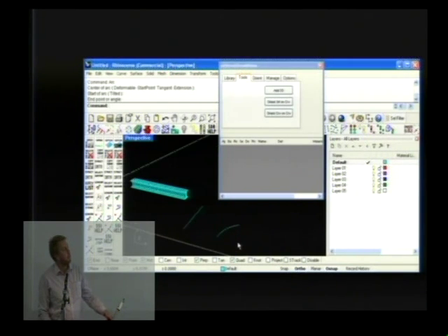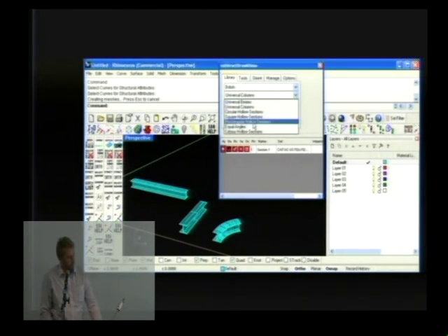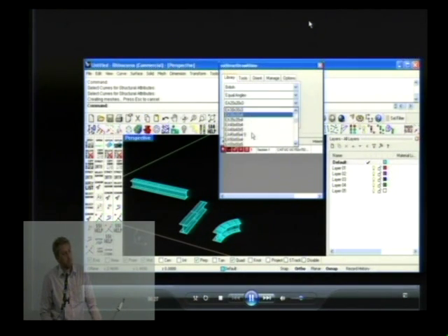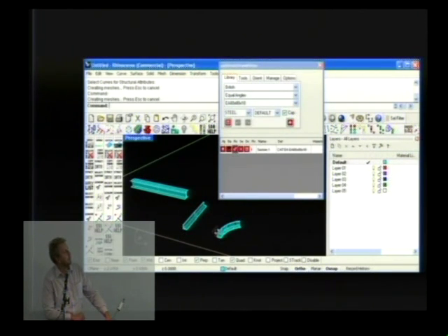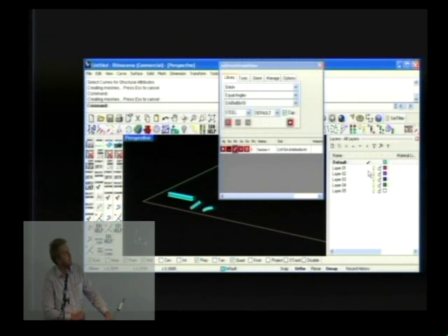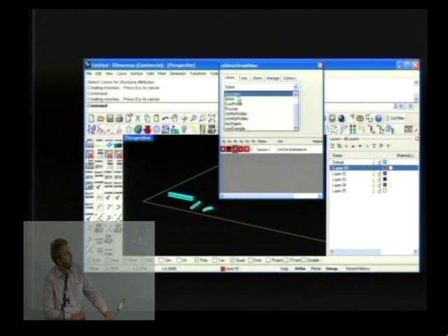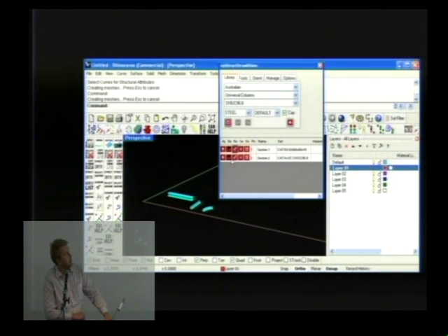When dealing with structure and using these in projects, stadiums, bridges, etc., part of what I had to develop was profile libraries and databases of sections that you'd use. Obviously, I've tried to pick the best aspects out of a number of software programs that I've used to create a better tool. It also works parametrically, similar to Grasshopper. So you can apply that section profile to centerline curves, whether on the center or the top or a particular location point on that profile section. And then you can parametrically change it. So if you update your table property, it redraws that section.